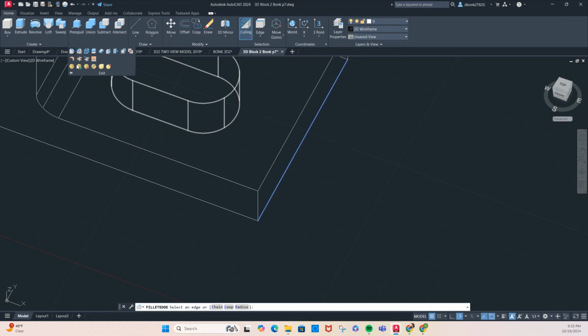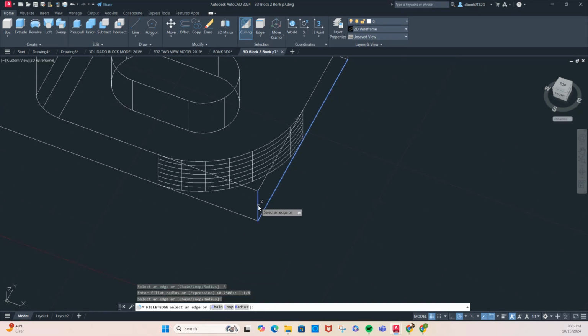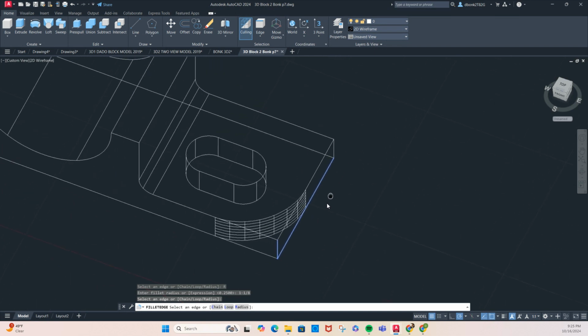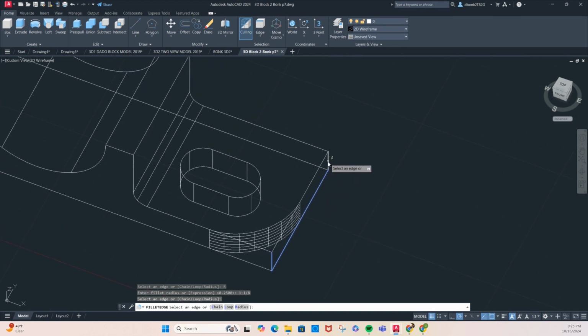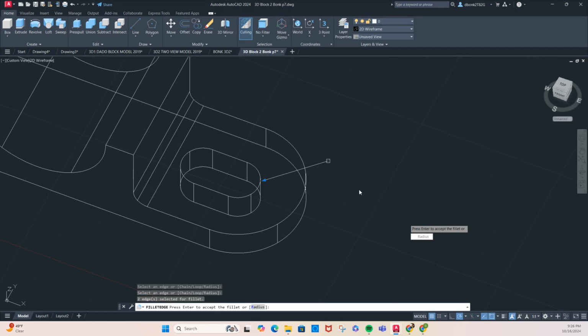So you click this fillet edge, click radius down here, tell it what measurement you need it to be, which is 1 1/8, 1 minus symbol, 1/8, like that. Enter. Click here, pressing the mouse wheel down to grab that and slide it down. Click there. You can select multiple edges always in these programs to fillet things. Hit enter. And we are done with that part.